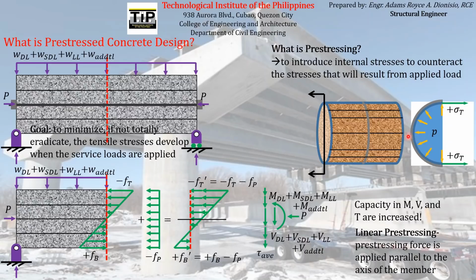The steel band will look something like this. And if this is prestressed, that steel band will impose another tensile stress on the wall. It will impose a prestressing stress, obviously, that will help this tangential stress resist the horizontal components of the pressure acting inside the tank or the wooden stave or the barrel.